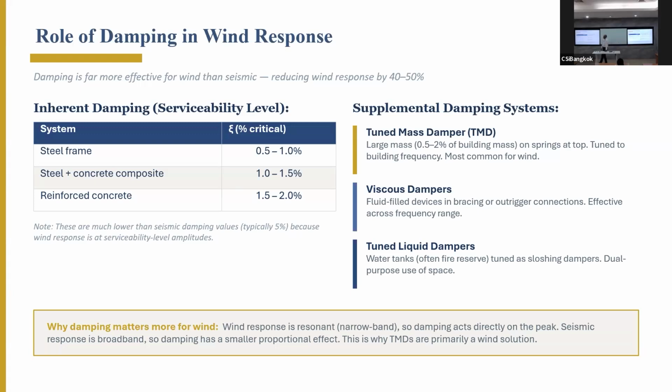So we use the damping, steel frame. We use even lower damping for wind than for earthquake. And why do we use lower damping for wind than for earthquake? So, for earthquake, immediately in the first two or three shocks, cracks will develop, and then the damping will increase. But wind is not like that. Wind is normally uncracked. So the original, fresh damping is still present, and we can't make a mistake on damping.